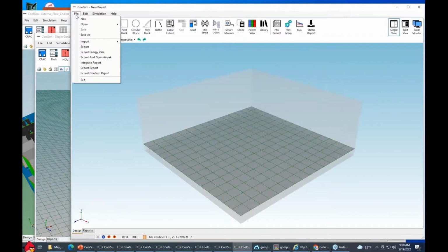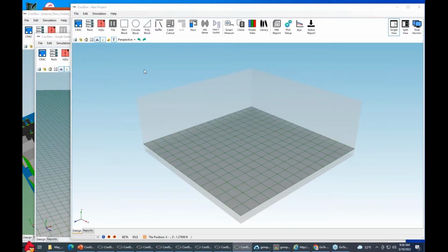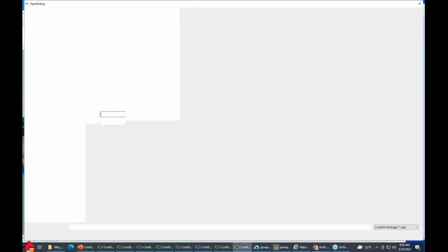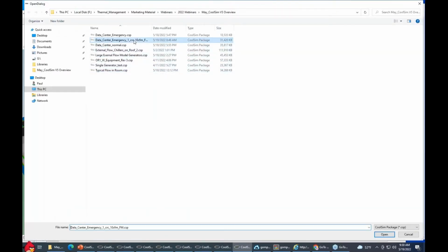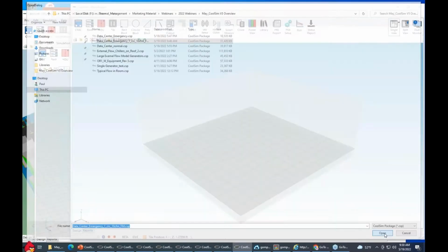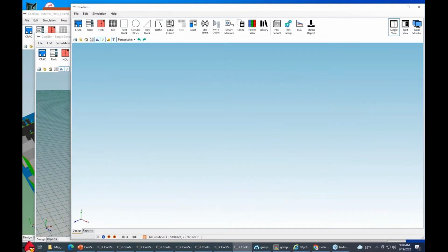And at the same time, we also opened up inlets on the sides of the walls. So here's my emergency case here. In this case, we brought in air from adjacent volumes, adjacent rooms, if you will, and used fans. So you're just modeling it as a fan, and you're assuming you have a constant temperature coming in. So that's an alternative method.